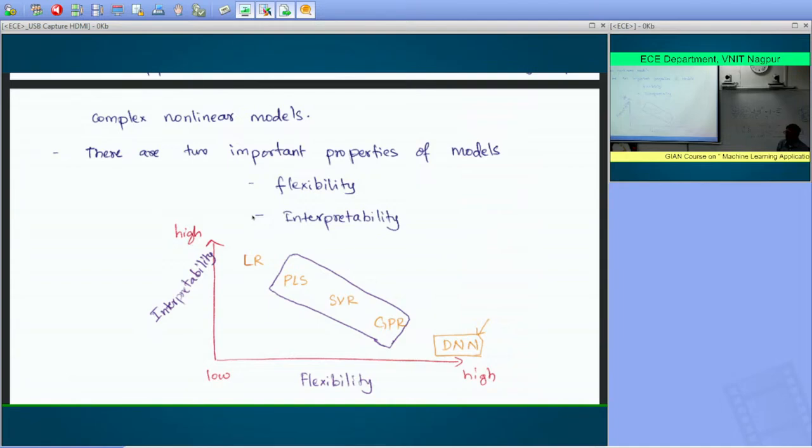But in most cases, you really don't know what this system is. You're always working with this one, okay? And this system that you work with will have some bias and variance errors. But you can eliminate them by building a data-driven model on top of your first principles model. And those models are called hybrid models. There are different ways of building these, but this is a hybrid model.